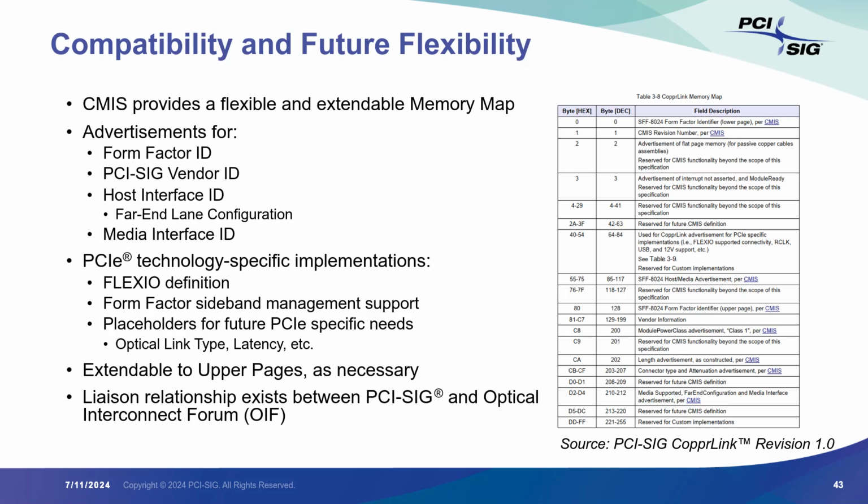Specifically to PCIe implementations with the Flex I/O definition, this would also be a place where you can advertise if and for what you're using those Flex I/O pins, as well as providing possible future placeholders for advertising certain things like optical link type, as these solutions could be extended to support active and optical cables, and attributes associated with those solutions, like latency, may be important to advertise to users that are trying to determine what's going on as they try to bring links up and go through qualification.